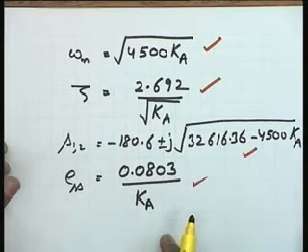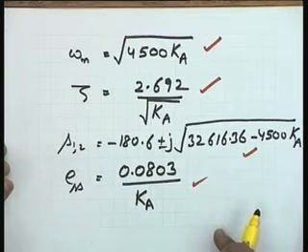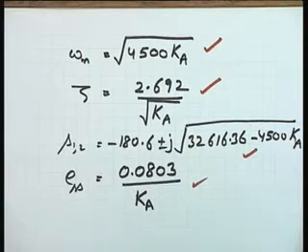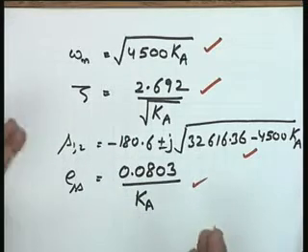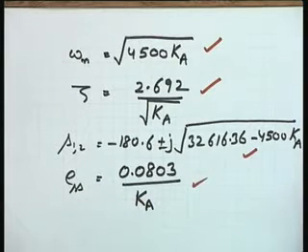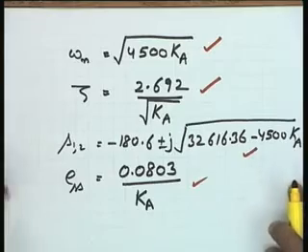Tell me please whether this steady state error is an error to step input or to ramp input. I have not written here. Should it be to step input or to ramp input please? No. For step input it is decidedly 0. How can I give it in this expression? I have not written for you, you have to note that this has to be ramp input, neither the step nor the acceleration, because I know that it is a type 1 system. For step input it is 0 and for acceleration input it is infinity. So, it has to be finite only for ramp input, and therefore, for ramp input the steady state error turns out to be this value. Okay. So, these are the basic relationships I have.